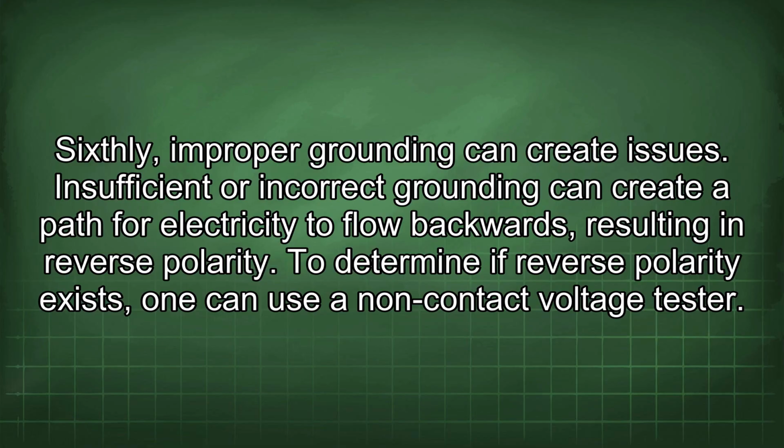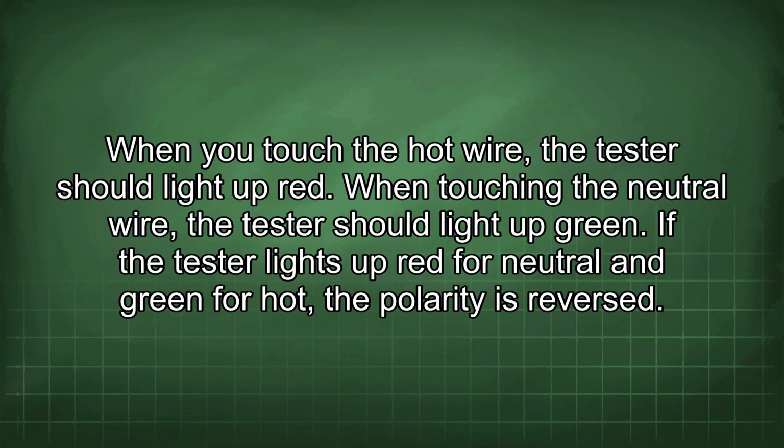To determine if reverse polarity exists, one can use a non-contact voltage tester. When you touch the hot wire, the tester should light up red. When touching the neutral wire, the tester should light up green. If the tester lights up red for neutral and green for hot, the polarity is reversed.